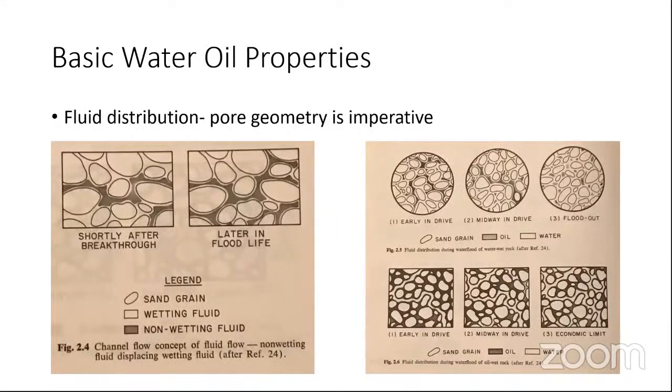For fluid distribution, the pore geometry is imperative, especially when determining water flooding projects. You'll notice the picture on the left shows breakthrough versus later in the water flood life, of where water is penetrating. And then on the chart on the right, you have your water drive early in the drive, midway in the drive, and then when the water's flooded out.